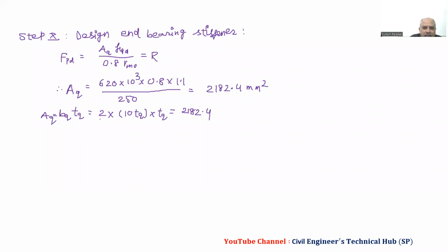Now, why are we considering these two? Because the vertical stiffeners we provide alternately, but these end bearing stiffeners are always symmetrical with the center. So we are going to provide them with sufficient end distance. We have this symmetry.